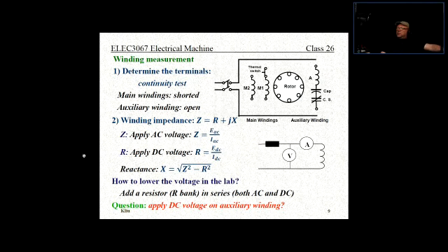There are different ones as far as electric cars. In some cases, the synchronous motor is applied. In some cases, there will be an induction motor, but with a wound rotor. And in some electric cars, there would also be DC motors, or brushless ones, because by varying the frequency you can control them. So there are different approaches to that.